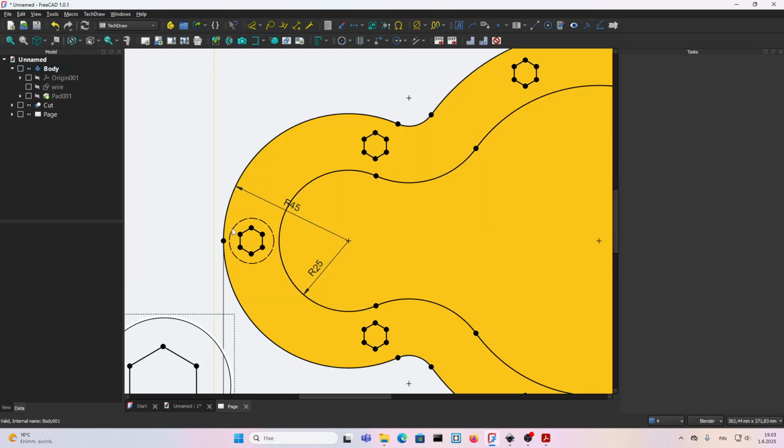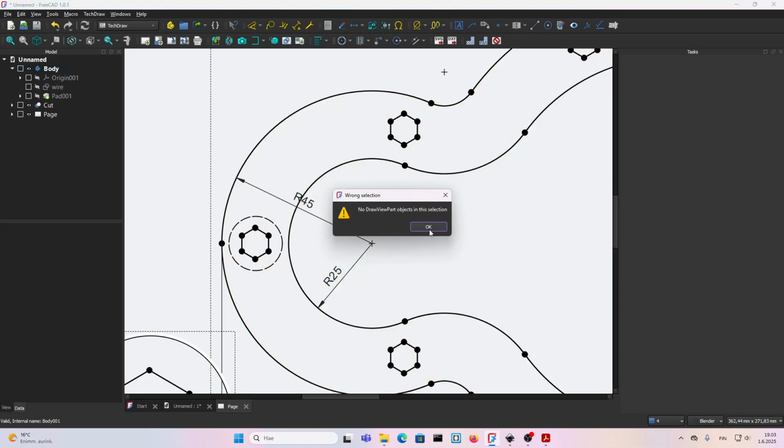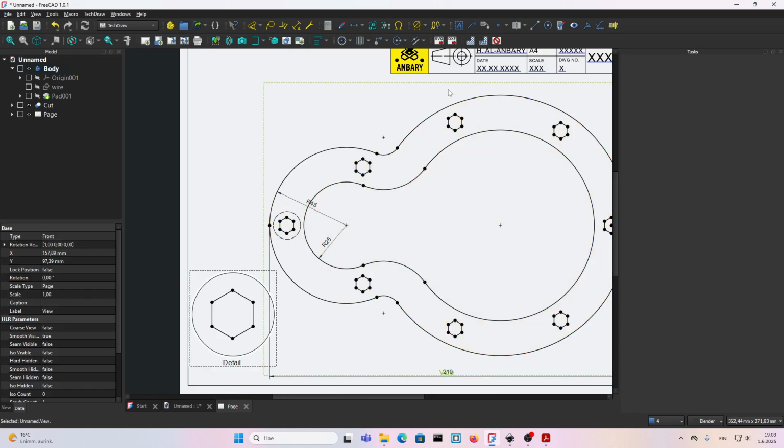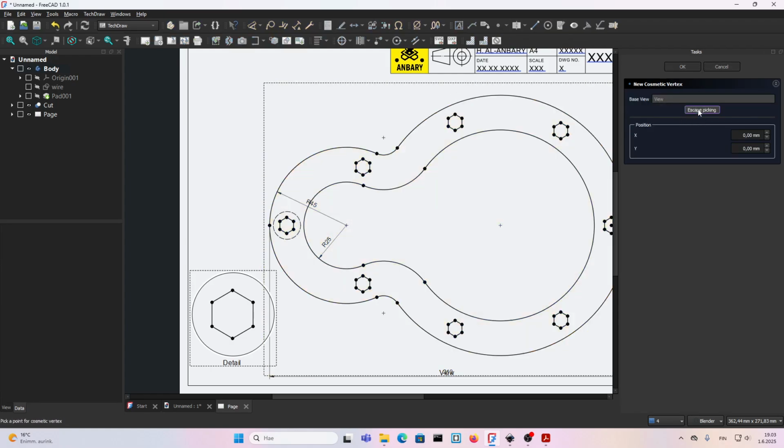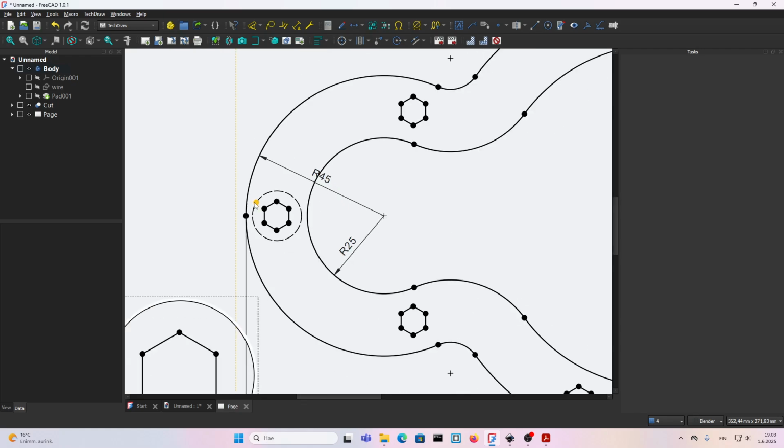On here, what I would like to do is add a vertex. Let's choose the part first. Choose the view, choose this vertex, point picker. Now zoom in here, and let's say click on here. Press OK. Now we have a vertex in here.